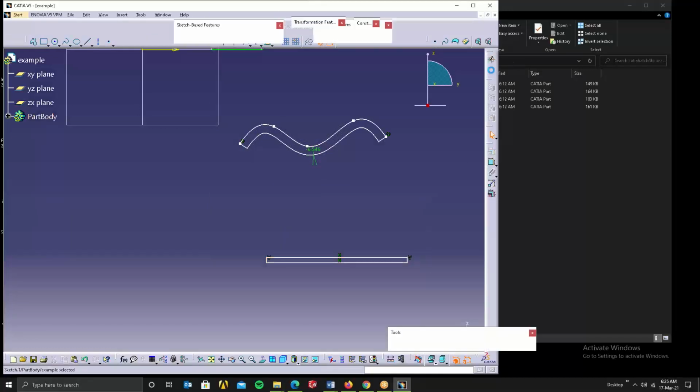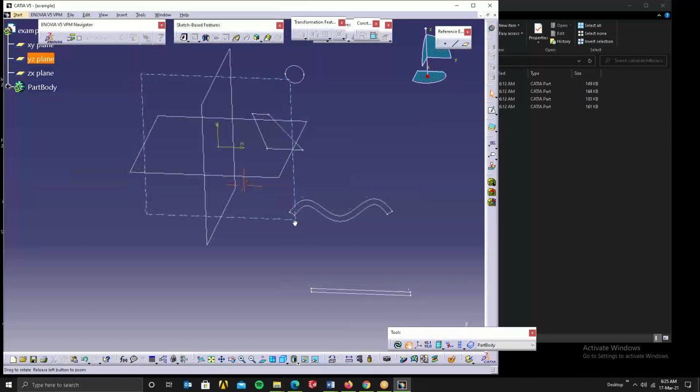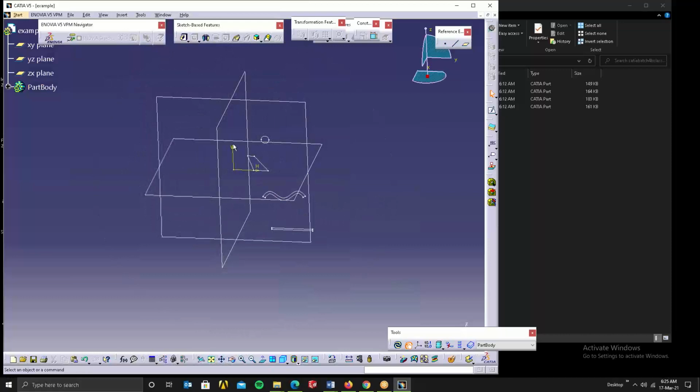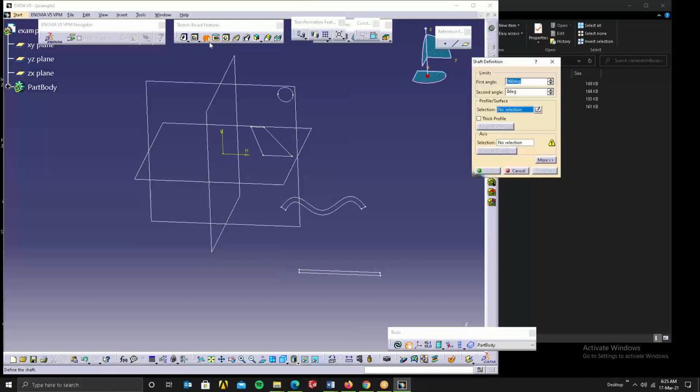So, I made a couple of drawings. Here, see, one more reason why I said center is that you'll have this. Using this, you can use this also. So use your revolve command. Use your selection, the sketches that you have done. Then the second thing is you have to select the axis, the center axis of rotation. The center axis of rotation is this vertical line.